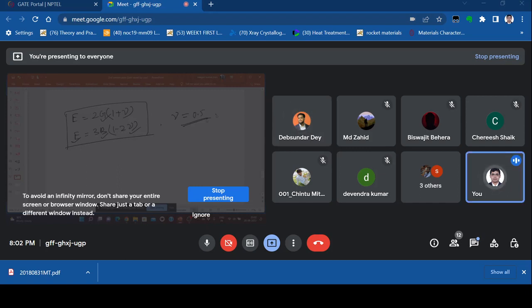Okay, so actually there is one relation as I wrote here, B equal to E over 3 times 1 minus 2 nu. You can actually prove it. So here bulk modulus must be positive always, because they are calculating change in pressure by volumetric strain.